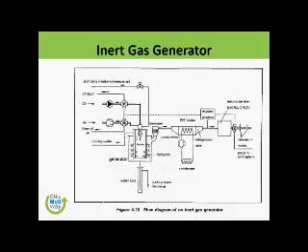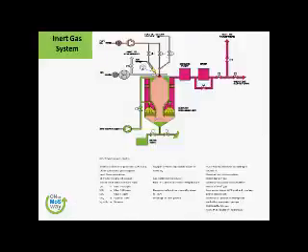So now this is a typical inert gas generator. In the last presentation, we discussed this generator, only this part. That is very simple, a burner burning, lifting up the gas, and of course it goes to the cooling system, oxygen analyzer, and so on. This is the typical IG generator or the IG system, folks.